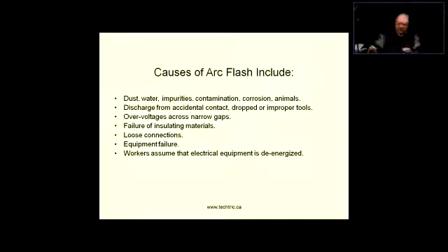Air does have resistance, and the more humidity in the air, the less resistance there is. Right. So if gaps are too narrow and there's too much voltage between them, an arc flash can happen between those two terminals. Failure of insulating materials, pretty much self-explanatory. Loose connections can cause an arc flash.